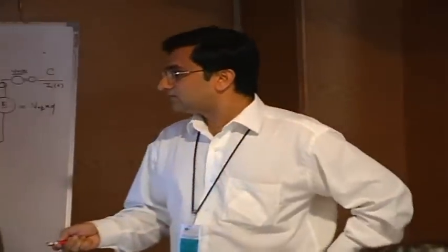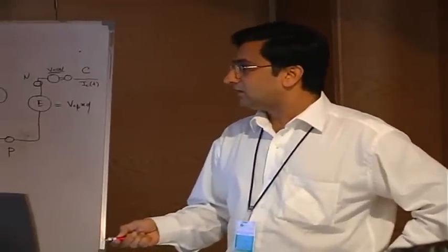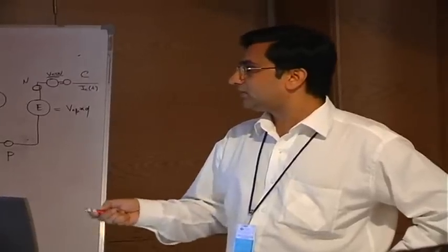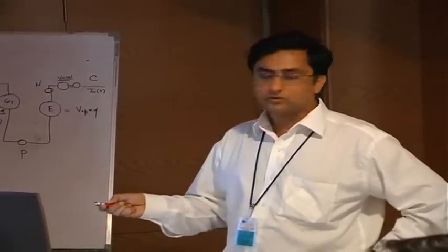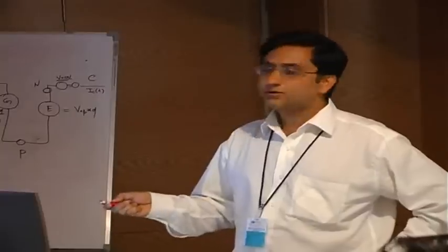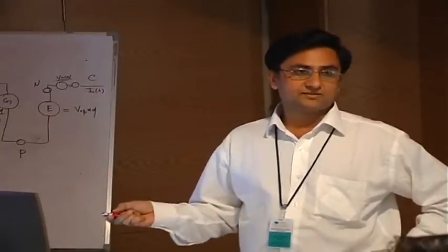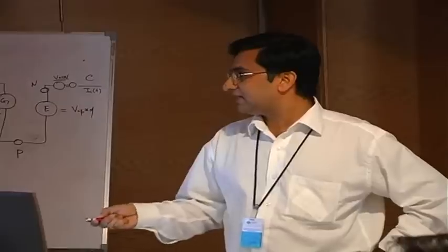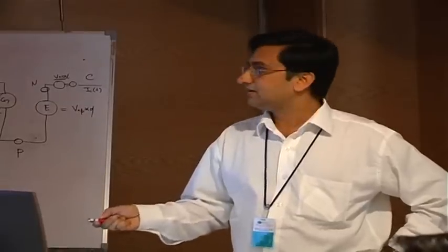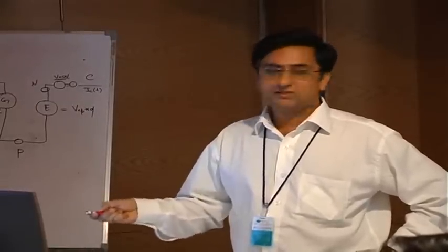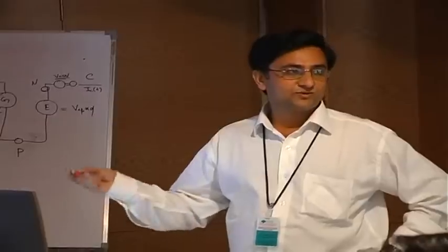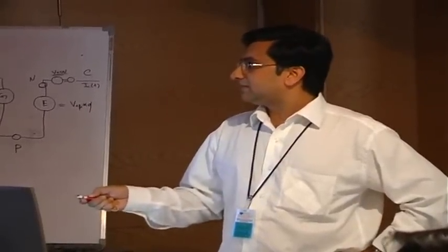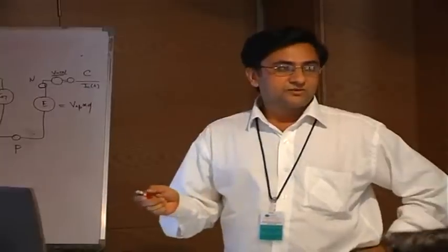Once we do this thermal analysis, then definitely we will hook this motor to the circuit and the load, and that is why Simplorer is coming into the picture. When I say this is a bidirectional coupling, it can go back and forth here. I will show how it goes and comes back. Now, this inverter or the controller will be connected through cables.